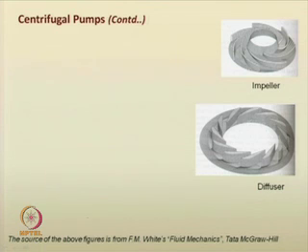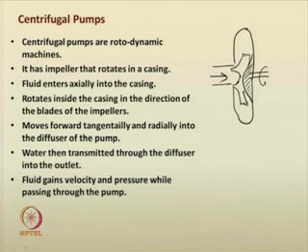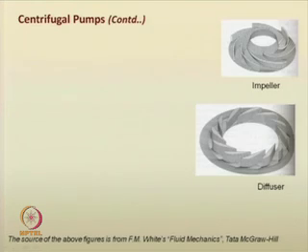So, here we have just given a sketch taken from F. M. White's Fluid Mechanics, published by Tata McGraw-Hill. There you can see a portion of the impeller. At the inlet of the pump, it consists of an impeller disc having impeller blades as shown here. You can see various curved impeller blades on that impeller disc. This is connected at the inlet.